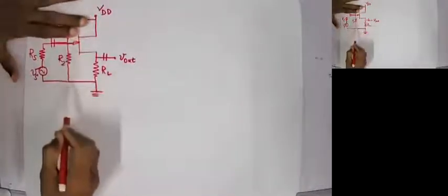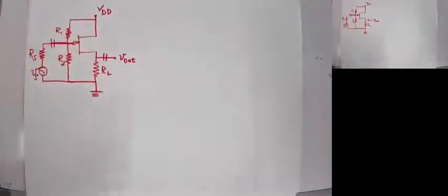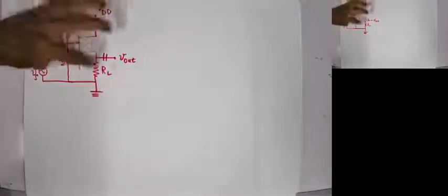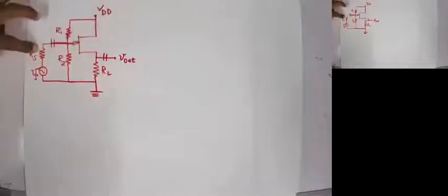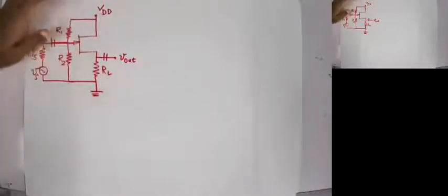Sometimes you may have the circuit without this R1, right? Only you will have the biasing resistor R2, depending on your problem. But anyhow, compared to the internal circuits and RL and RS, R1 and R2 or the parallel combination of R1 and R2 will be much higher, right? Much higher. So now we are going to draw the equivalent circuit of this field effect transistor circuit, right?